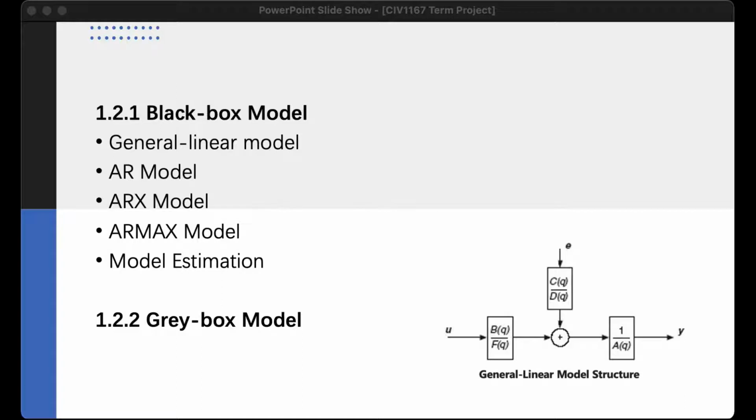By plotting the zeros and poles and looking for cancellations, you can reduce the model order. The resulting order of the poles and zeros is a good starting point for ARMAX, with these orders used as model parameters and first or second order models for the noise characteristics.